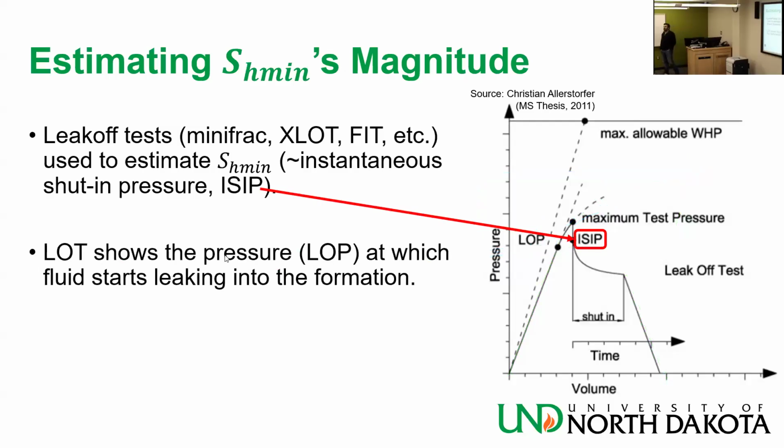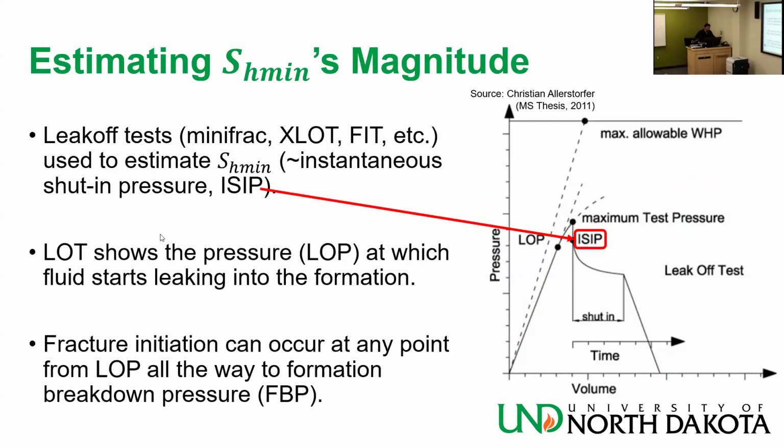So the leak-off test, LOT, shows the leak-off pressure, LOP, at which the fluid starts leaking into the formation. Fracture initiation can occur at any point from leak-off pressure all the way to formation breakdown pressure.